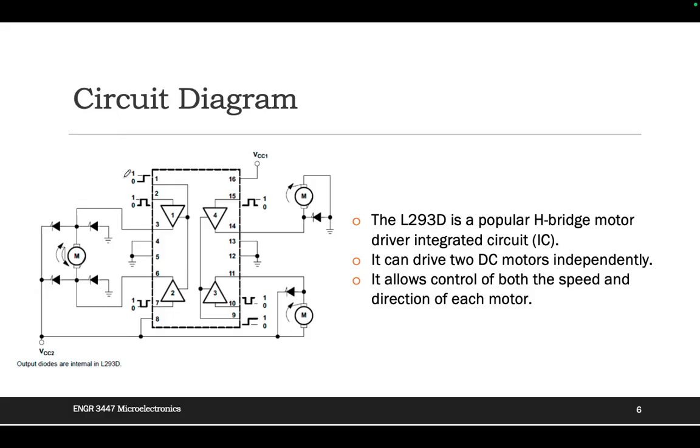You just connect the motor to the chip, give it power, and give signals to different pins. Using one motor, or 2? At the beginning you can use one, just make it run in different directions. But finally you need 2, because today we will build a small robot base.